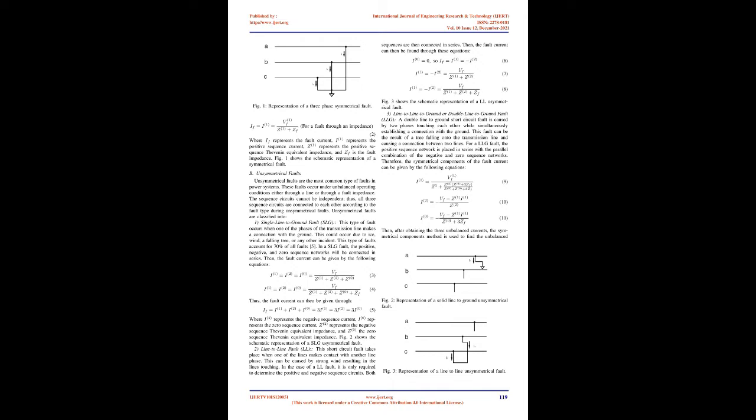Weather conditions. As discussed in the previous section, unfortunately, nature has a high chance of causing faults. These causes include faults induced by lightning strikes, heavy rain and wind, snow or ice accumulating on the transmission lines, and finally insulation contamination due to salt or any other pollutants.